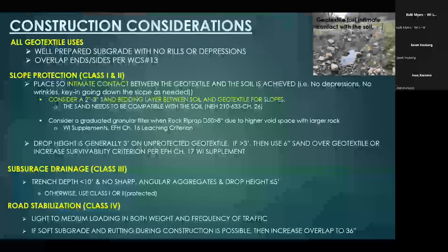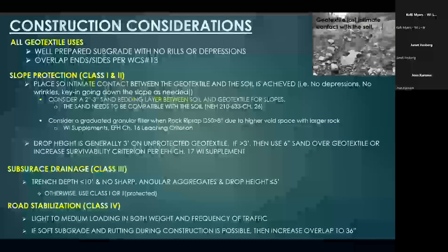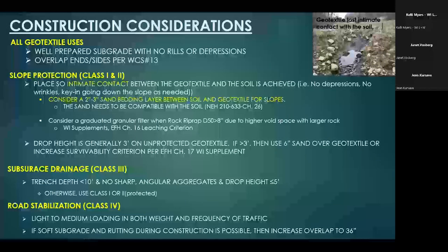Hey, Construction Janet, I do have a question. Sure. Are sock wrapped tile appropriate in any NRCS projects? I would say no, because sock is essentially a geosynthetic or geotextile. So no, I wouldn't use sock wrapped.